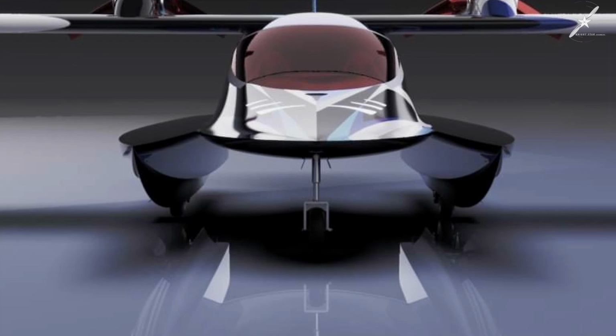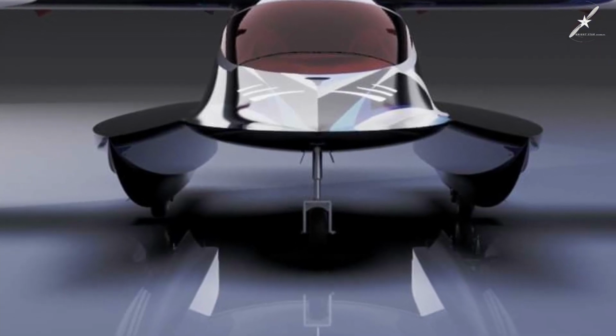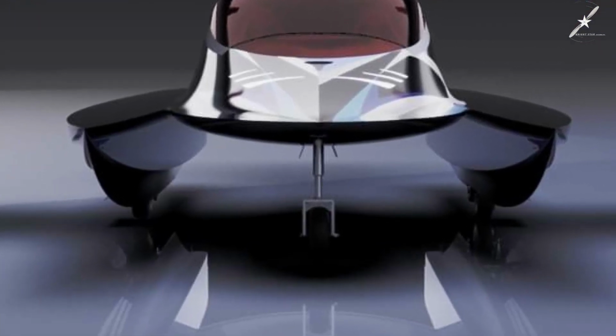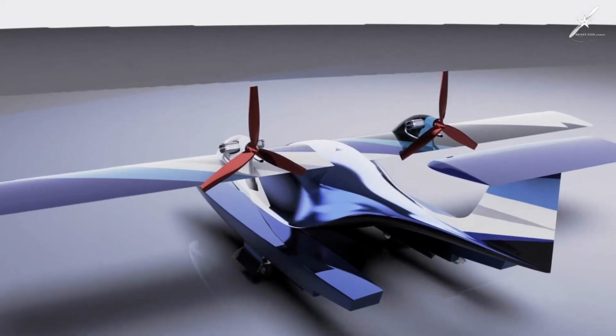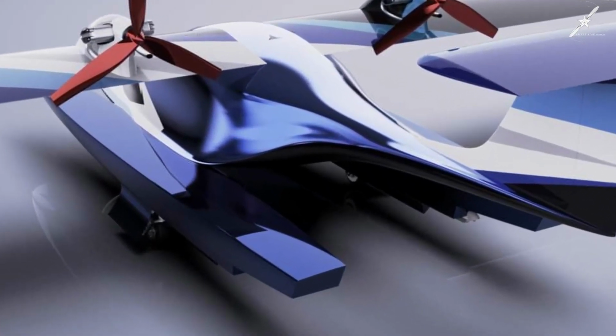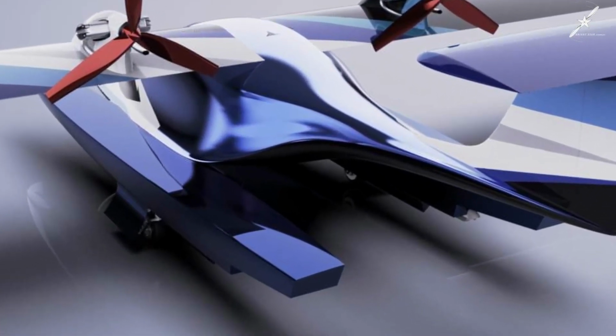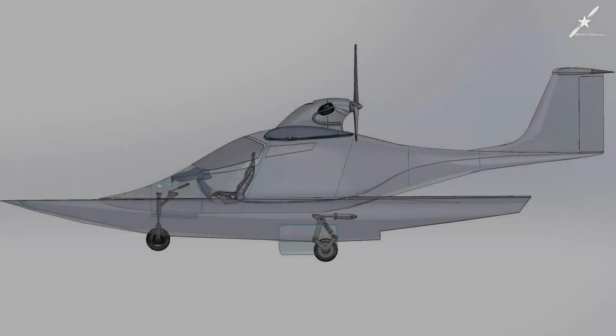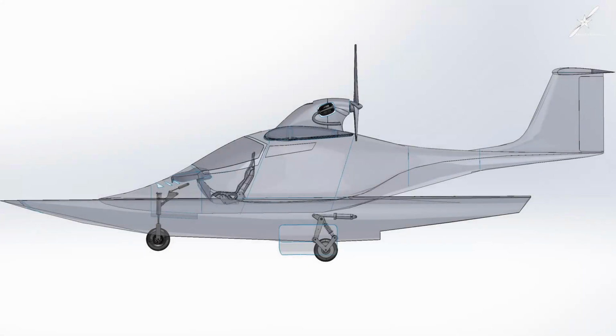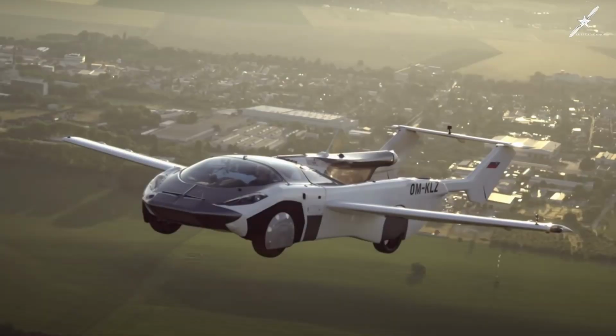off the water faster. The front opening between the water and the nose is larger than the back exit. This causes a high pressure area between the water and the bottom of the fuselage. So, at this point, I don't see it as an issue. Here is an example of an aircraft that has a massive flat bottom area, which is much larger than mine, and it flies fine from what I've seen and read.